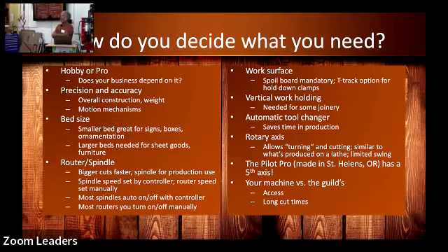Or a shroud, or both. And a point that Dave makes on a regular basis now that he's stuck with a router-based machine instead of the spindle he's used to is he's got to turn the thing on and off by himself, as opposed to the controller turning the spindle on and off. And also, typically the controller, if there's a spindle, will control the speed. So in speeds and feeds, the speed is set. I've got to turn the dial on my router in order to change that.